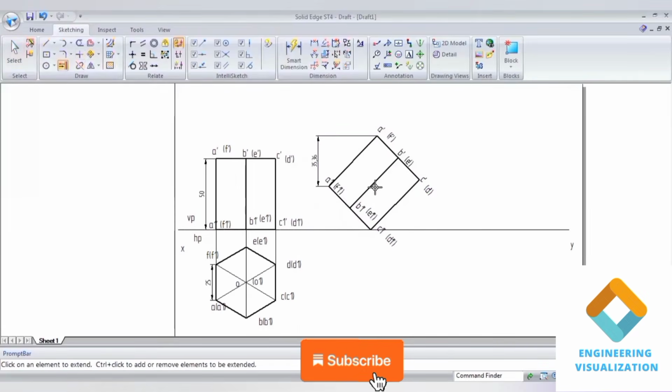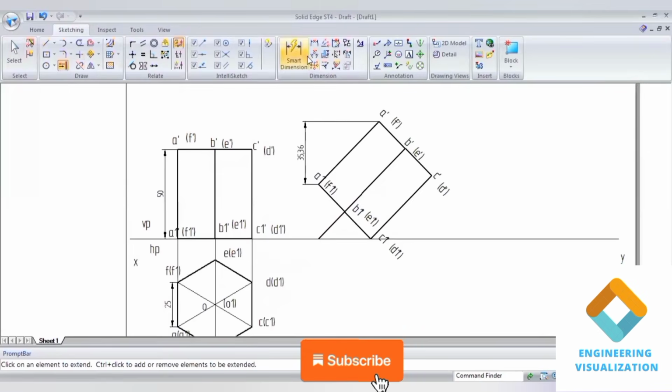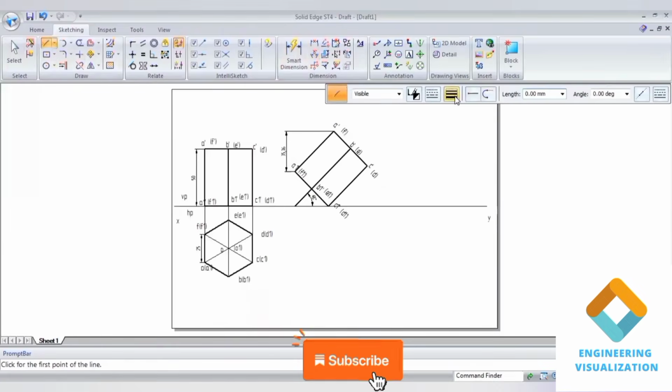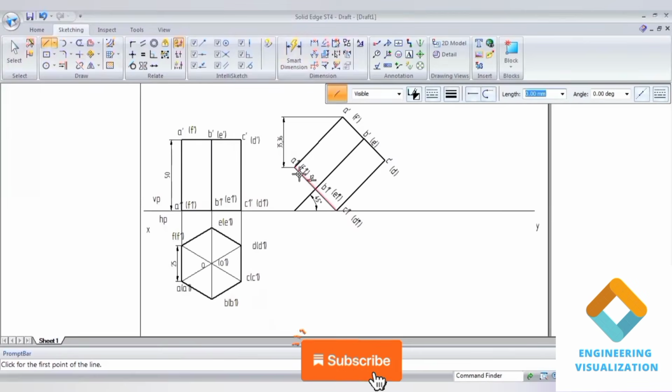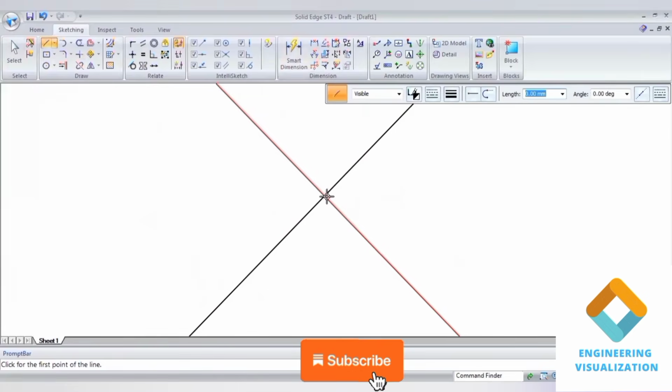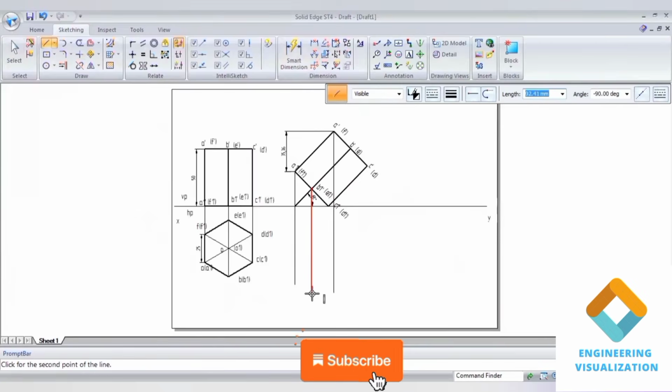Now extend the axis, find the angle, and project downward to complete the second position top view. So draw the projection lines downward here, to complete the second position top view.